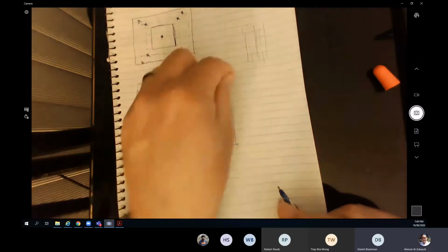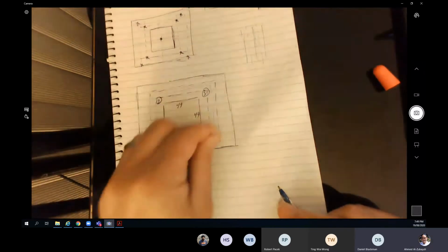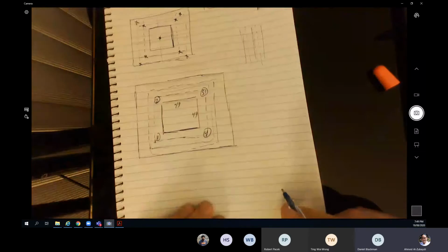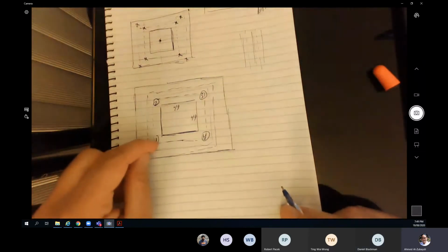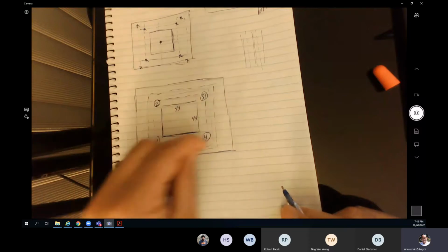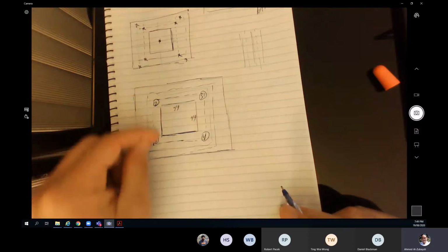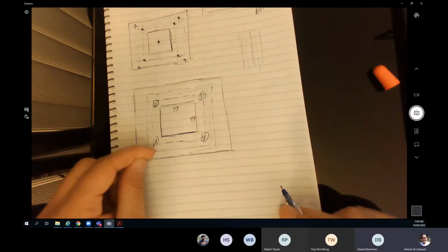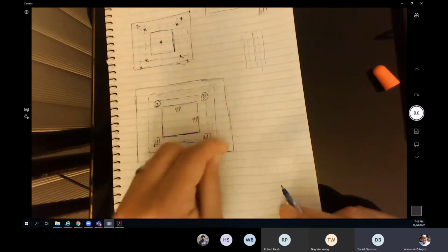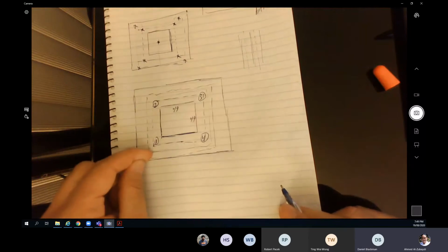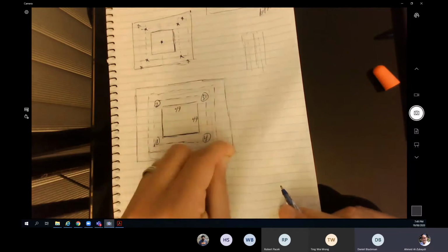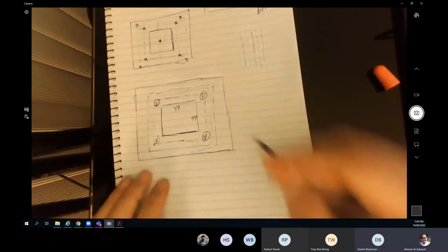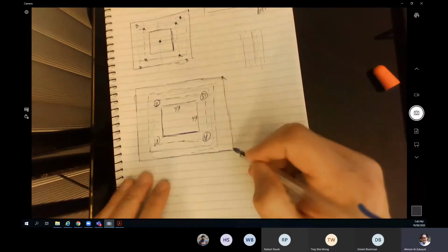You can start from the outside. This is just for planning purposes and keeping it as easy as possible. I just want you to find the locations with an easier method. Square, the small square first, then you enlarge it, do the second larger. So it's going to be something like doing the pocketing, and then just enlarge it with a bit of an overlap to avoid leftover material. Until you finish at the end by moving through these points.